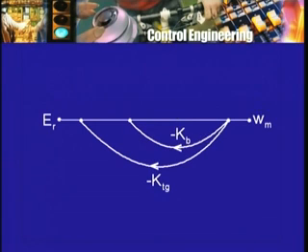One of the loops goes from omega m through a transmittance minus Kb, that is the back EMF loop, so to speak. The other goes from omega m through minus Ktg, that is the explicit actual physical feedback signal, the tachogenerator voltage output.